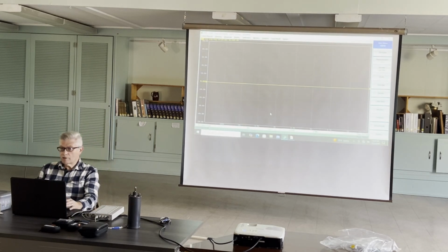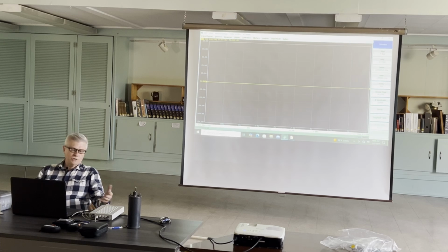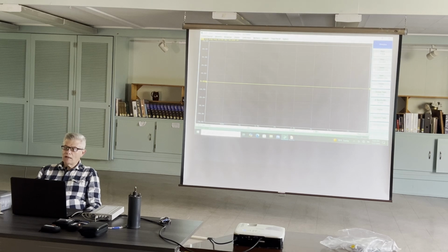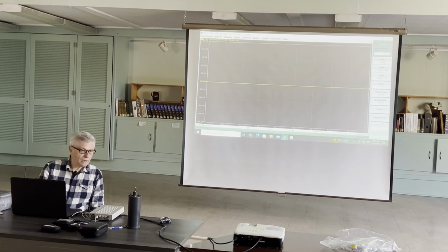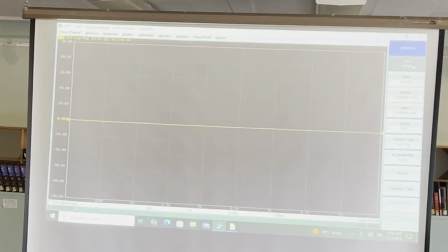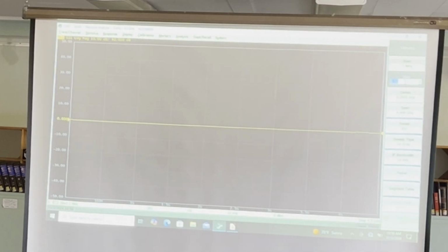So what we're going to do is go through and set our stimulus, which is the band of frequencies we're going to operate on or have this thing measure. So we're going to do a basic calibration. The first thing you want to do is put your low frequency in. Nope, didn't like that. Why not? Oh, that's because I had the shift key on. There we go, 1 megahertz. And we'll stop it at, I don't have anything more than about 500 megahertz here today, so let's do that.